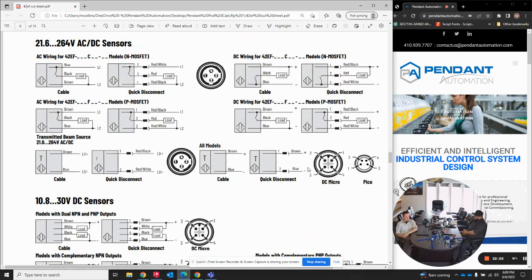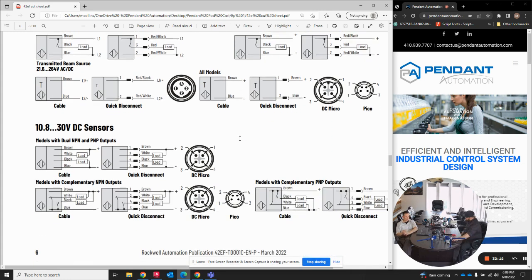So talking about 120 volt photo. First off, let's talk about 24 because that'll make more sense. Then I want to talk about 120, and there's a field caveat there that I definitely want to make sure we go over. So 24 volt wiring, you have two different types. You have NPN and PNP, and that generally is transistor talk for negative-positive-negative or positive-negative-positive. And that's really how the transistor is terminated to that input and output.